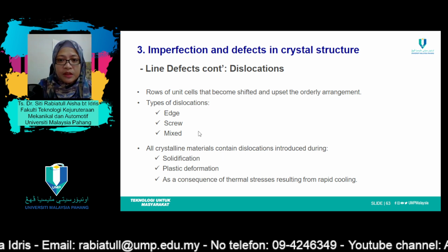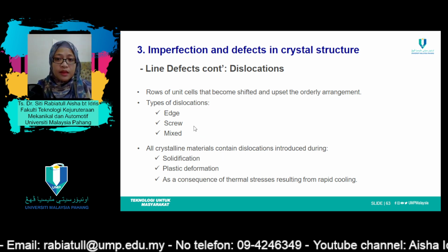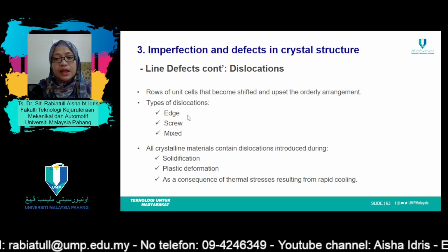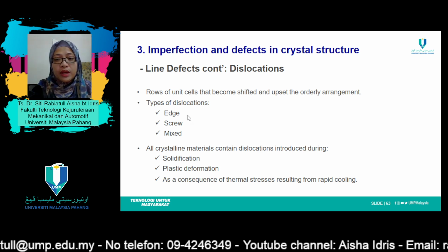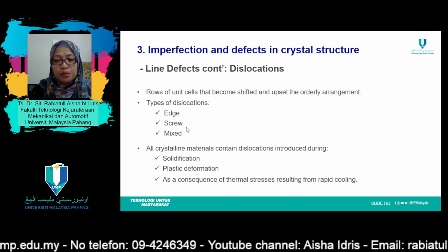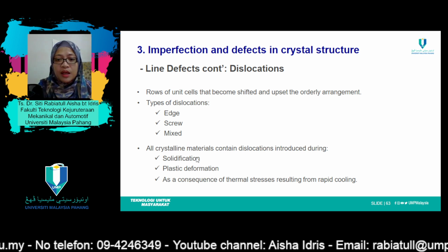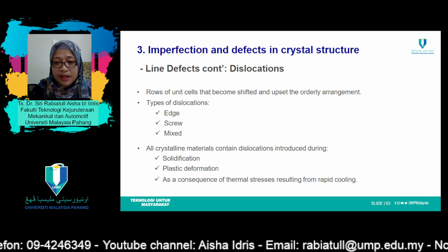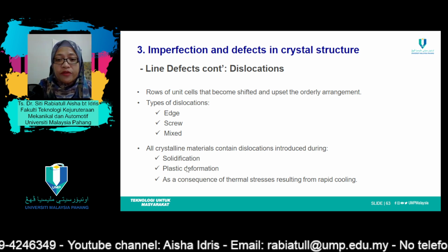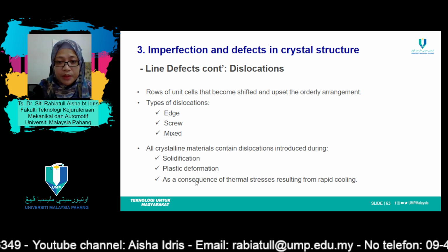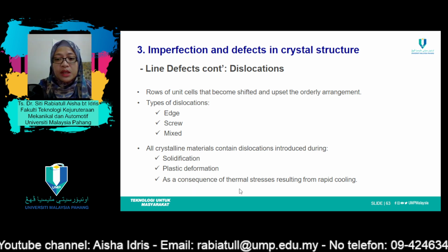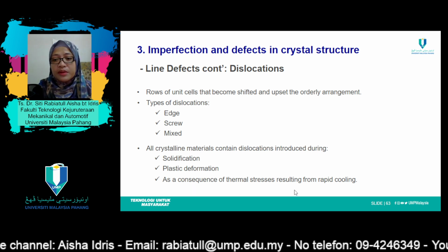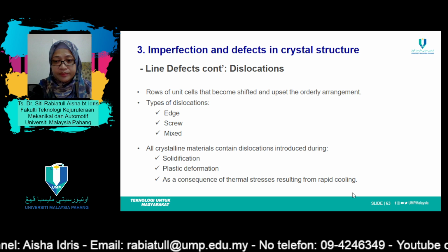And the types of dislocation that we can find are either edge dislocation, screw dislocation, or a mix of both, and it exists during solidification or plastic deformation, or as a consequence of thermal stresses resulting from rapid cooling.